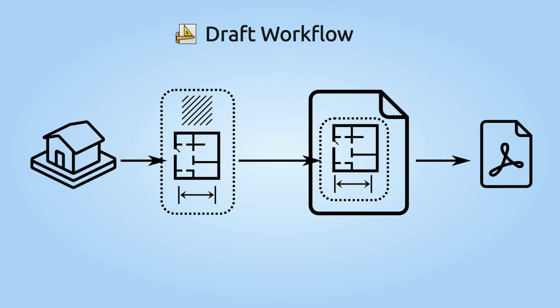Most of the work of creating construction documentation using this workflow is done in the 3D model space, and then the drawing is placed on the sheet where only the title block is filled in. The advantage of the draft workflow is the flexibility. The user can achieve any desired graphical output using powerful Draft tools.